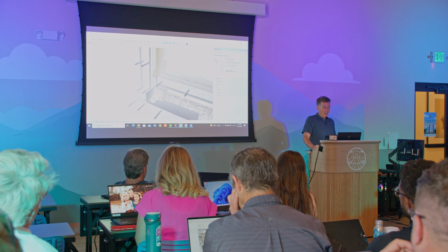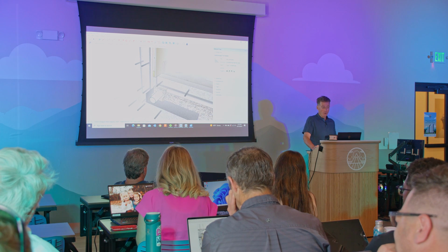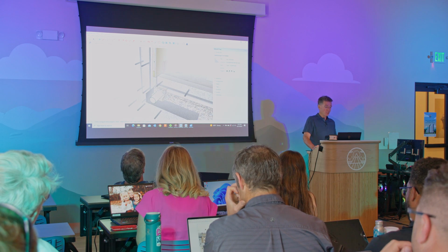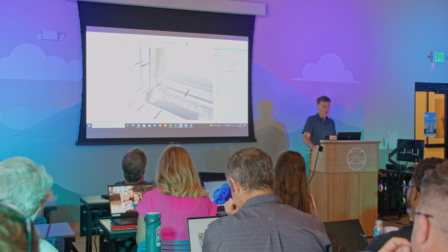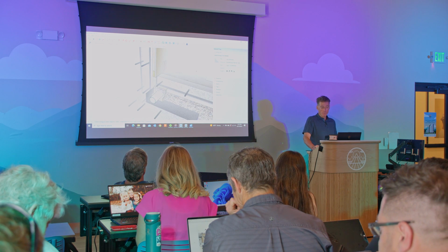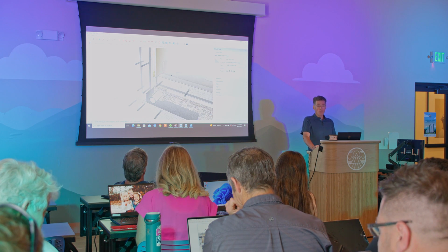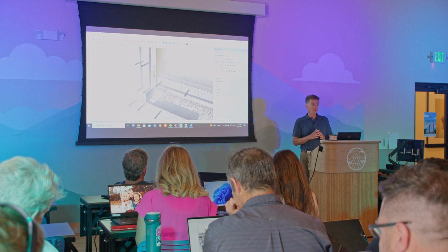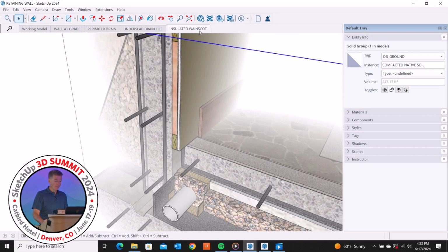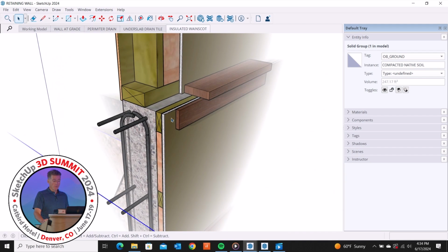Morbid, I know. In this case, the detail is showing the interior finish where we have the furring strips, the 1.5 inch of rigid insulation, and then the drywall and baseboard and any finish that we have. A lot of times I won't necessarily show the exact finish, I'll just say floor finish, see schedule. In this case, this also captures, if this doesn't go full retaining at some point, we will have an issue to deal with where we have a step in the wall, and we either fur that out just to make it one wall, or in a lot of cases we'll do a little wainscot detail in that room. So these are all great.